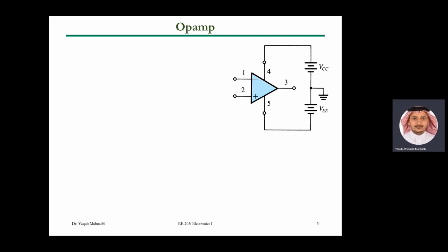We have the inputs: this one here is the non-inverting terminal, the non-inverting pin, and this one is the inverting pin. So these are inputs. It should be obvious that you have your input from this side, not the other side, right? And then you have the output, which is the V output pin. And then we have 2 power supplies: plus 15 and minus 15.